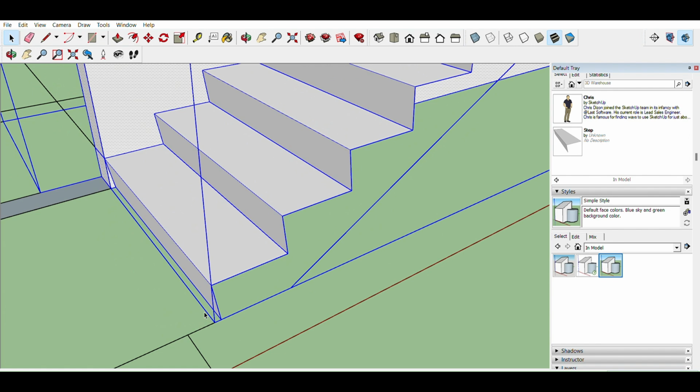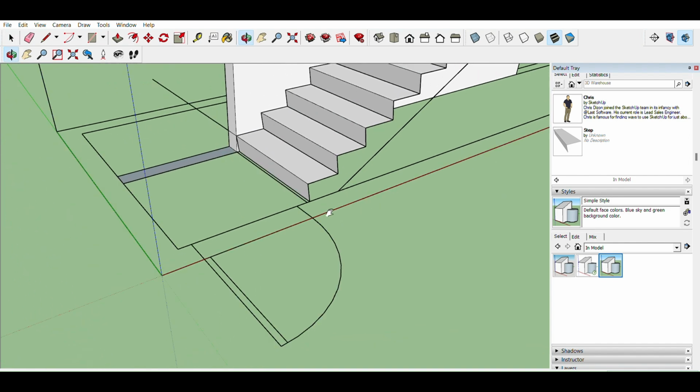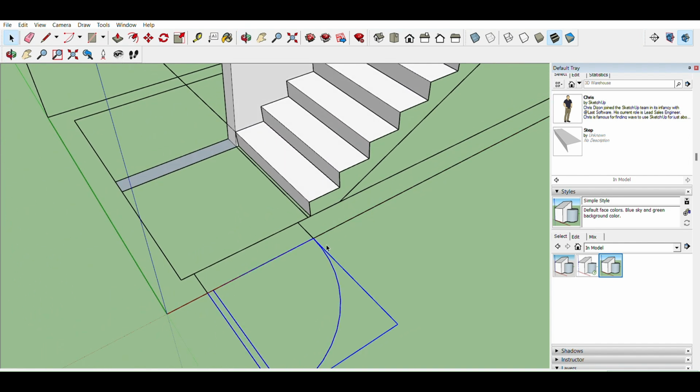I want to keep that 4 inches. So the handrail is going to extend from nosing to nosing, that same distance down here, and then plus another 12 inches out, which is pretty nuts. Pretty nuts. Let's not set the geometry based on that. Just figure out what we want to do with that later. There's something I could do with that later.